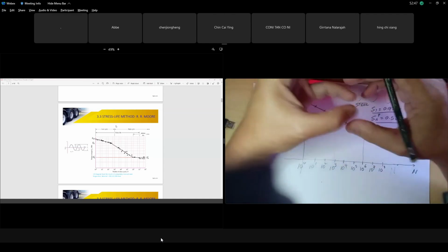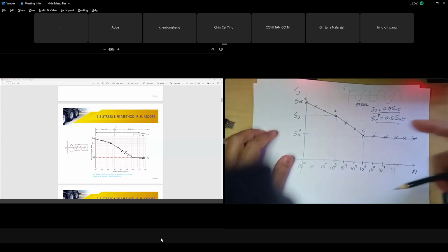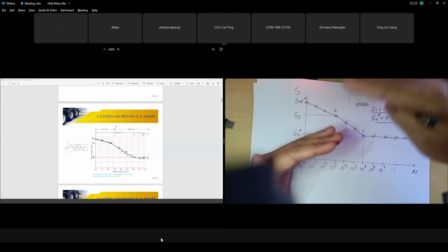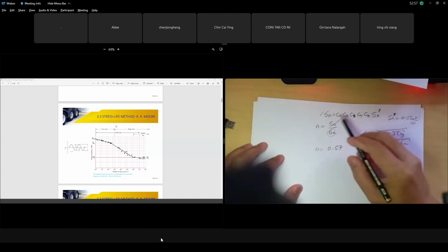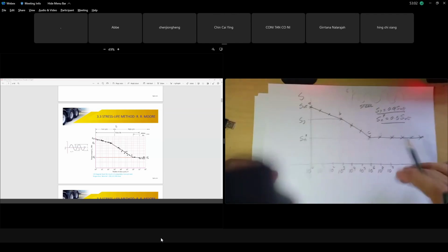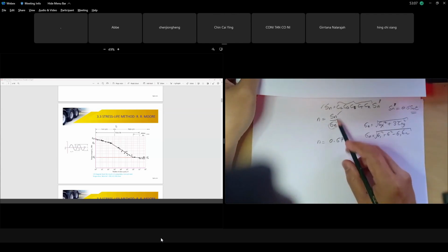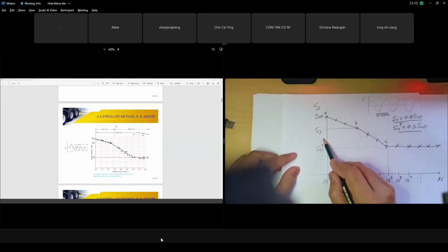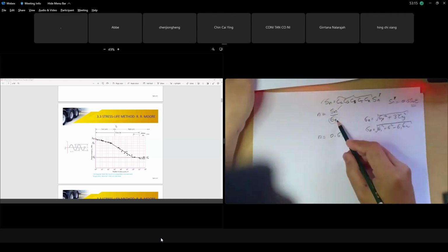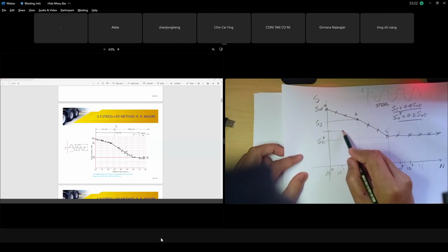Your case, the shaft, when you do analysis, the plot of your graph of log time is the same behavior as this, but a little bit scaled. That's why the modification factors I told you about, CL, CG, CS, all these modification factors. The plot of the graph is the same. So this is your endurance limit, your Sn. If your denominator is greater than Sn, it means your strength is somewhere above your Sn. Understand, class? The strength you calculate, sigma E, is somewhere above your Sn, because this is your Sn value. So you can do this log 10 graph.